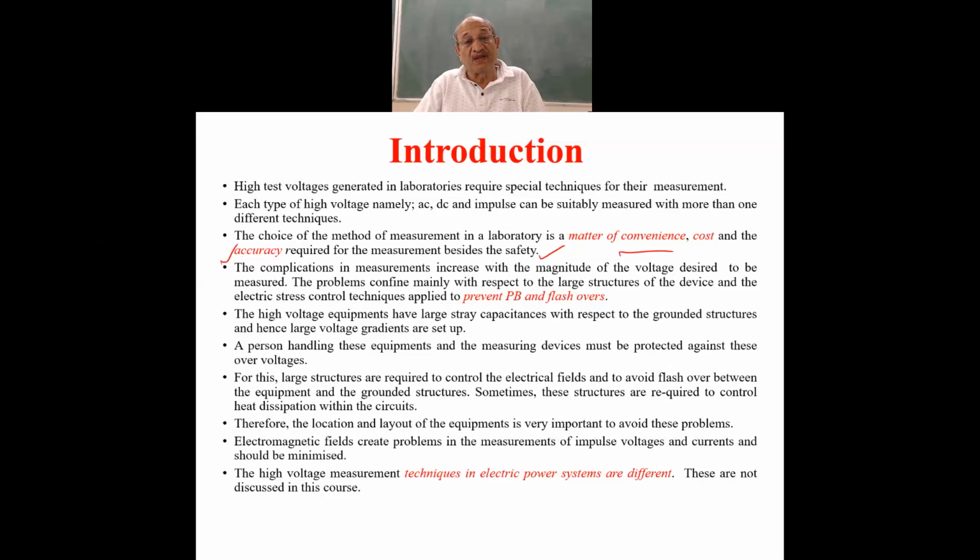As we have been mentioning, you can make a connection of high voltage with just a simple thin wire. But when you apply very high voltage to the thin wire, there will be partial breakdown around it because of the high field intensity. So, what is the solution?